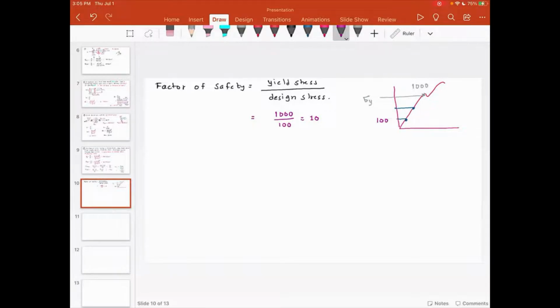If you are going to design an aircraft, and if you use a factor of safety of 10, then that aircraft is going to be super heavy, and it will increase the cost, the fuel consumption, maintenance, and so on. So you have to strike this fine balance that you want the design to be safe, but don't over design to such an extent that it actually diminishes the very purpose of the design.